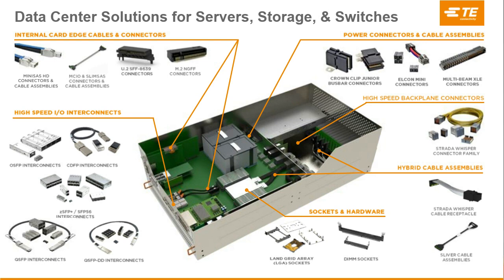Yeah, so I think it is clear that as the power density continues its climb, right, there will be a brick wall that forced air cooling runs into, between the efficiency of fans, the noise generated by fans, and there's only so much heat load that forced air will be able to do.